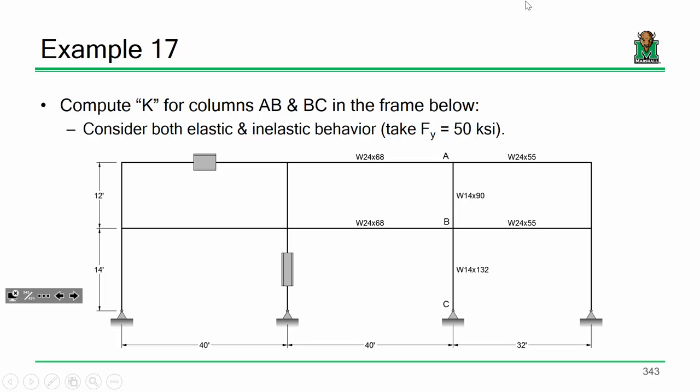What I am saying is that this adjustment will not only help you, but it also adjusts your K values to better reflect reality. I guess another way of looking at it is if we ignored all this AISC spec and just used elastic buckling, in most cases we would be unconservative. So using tau really just brings our math closer to reality, and it has the added perk of upping our capacity a little bit.